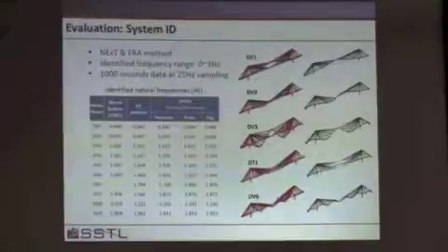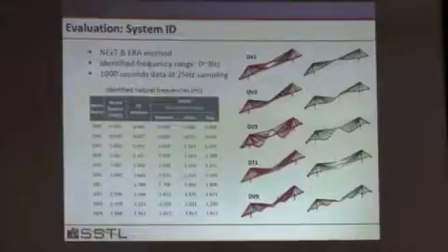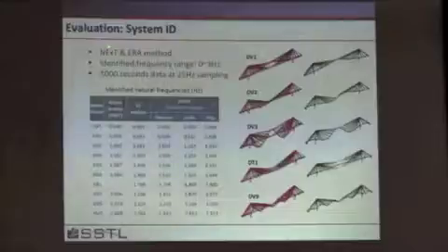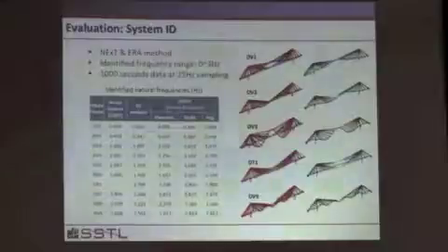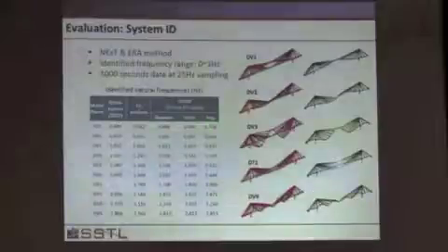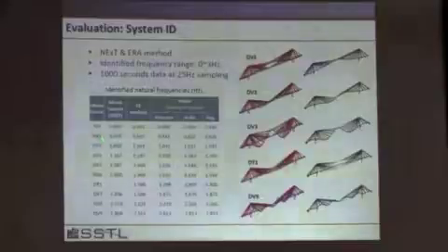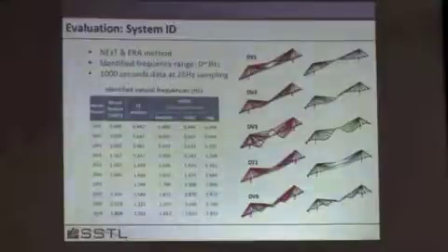On the left-hand side are the mode shapes that were estimated based on this NExT-ERA method, the natural excitation method that I mentioned to you before. And we did some things with decentralized modal analysis that would allow us to get these behaviors without collecting all the data. And what you see, this was in 2007, a wired system. This was our finite element analysis. And this was the collected data during the typhoon.